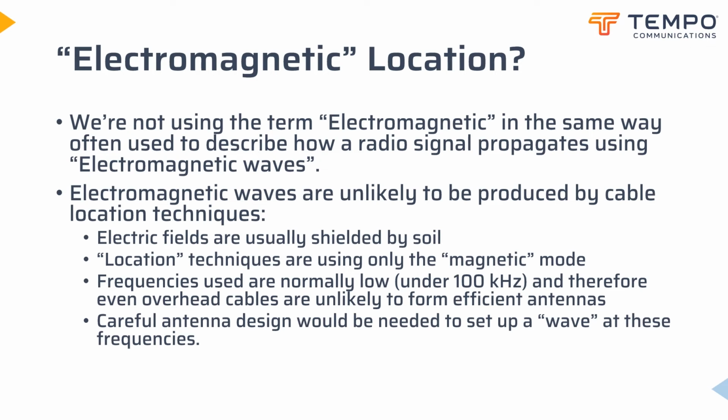So on a longer overhead cable run, there is a chance of a small amount of energy being transmitted. The levels are likely to be small due to the limited height of the telephone poles compared to massive low frequency antenna systems. But when detecting electric potential, then little current is flowing and a wave will not propagate. To get electromagnetic waves to propagate efficiently, you need an antenna, something that combines the electric field and the magnetic field to form a propagating wave. Everything you've seen today is part of electromagnetics. The key thing is to think about the fields and how they affect nearby objects.